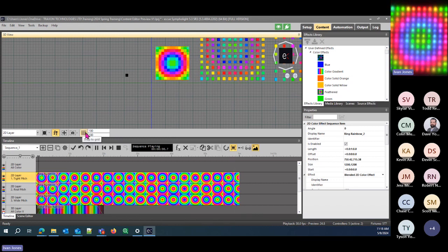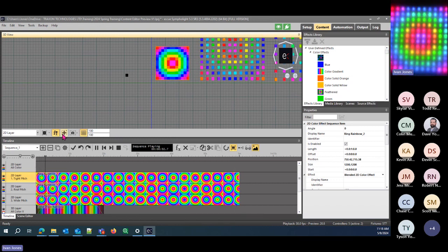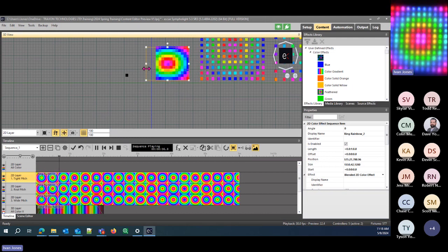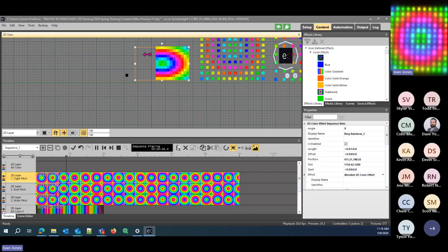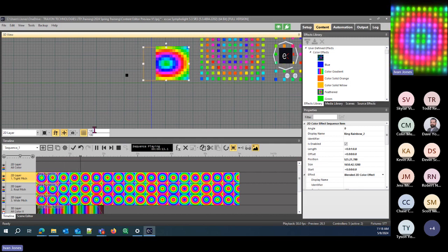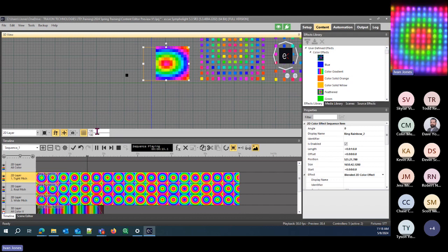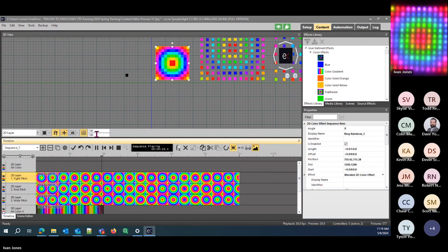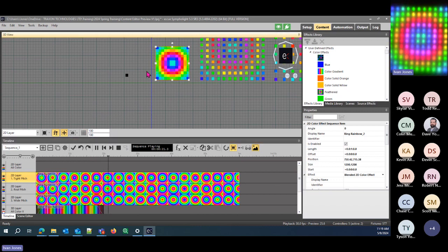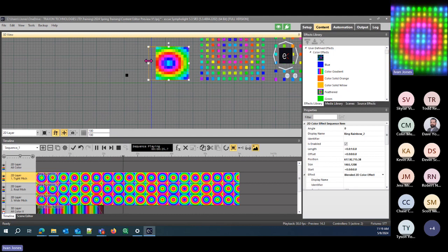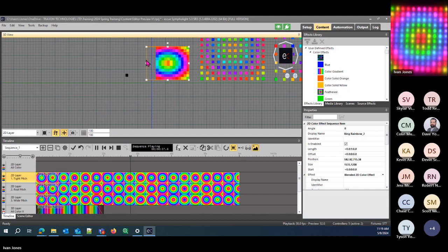And then we have the snap to grid, so I can make it so when I'm editing these frames, instead of smooth scrolling, they snap to this grid that is set here. So that's 100 pixels by 100 pixels. Sorry, 100 millimeters by 100 millimeters. Generally, I will work with just no pixel snap.